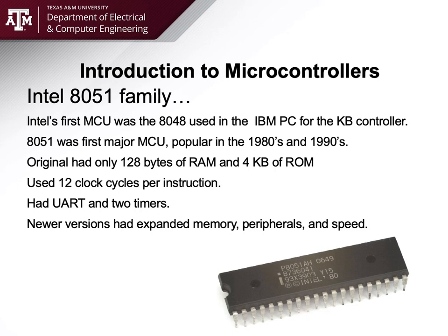I've actually done some complicated processing of some algorithms to determine settings of certain oil, gas, and servo valves and things like that, all with an Intel 8051, one of the original ones, and it is non-trivial to do that. You get very creative in determining how to do scaling of your math so that everything can still be integer math and not floating point math. Because floating point, if you remember from doing ECEN 350, floating point math is very expensive in the sense of computational cycles and also the amount of code it takes up to support that format.